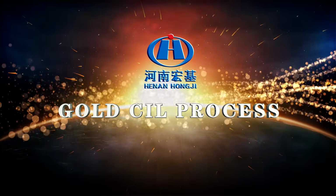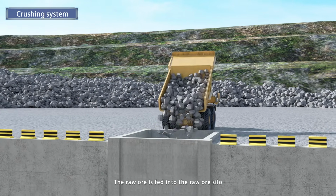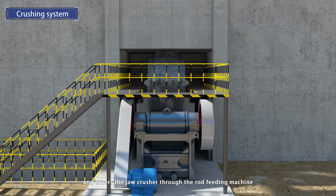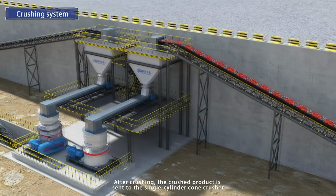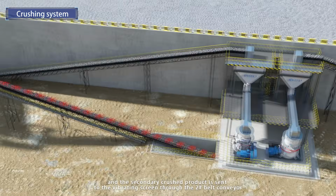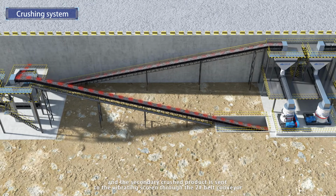Gold CIL process. The raw ore is fed into the raw ore silo and enters the jaw crusher through the rod feeding machine. After crushing, the crushed product is sent to the single-cylinder cone crusher for secondary crushing through the one-belt conveyor, and the secondary crushed product is sent to the vibrating screen through the two-belt conveyor.